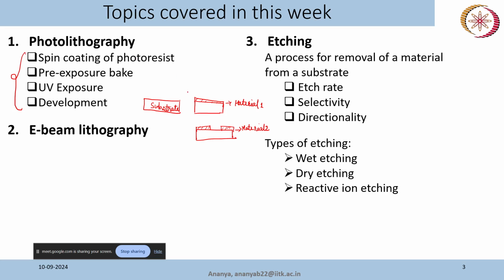For example, I was doing lithography today, and in that process I was using 6000 rpm for 60 seconds for the photoresist that I am using. That timing and speed will be different for different photoresists, and it was giving me a 4 micrometer thick photoresist on top of my substrate.